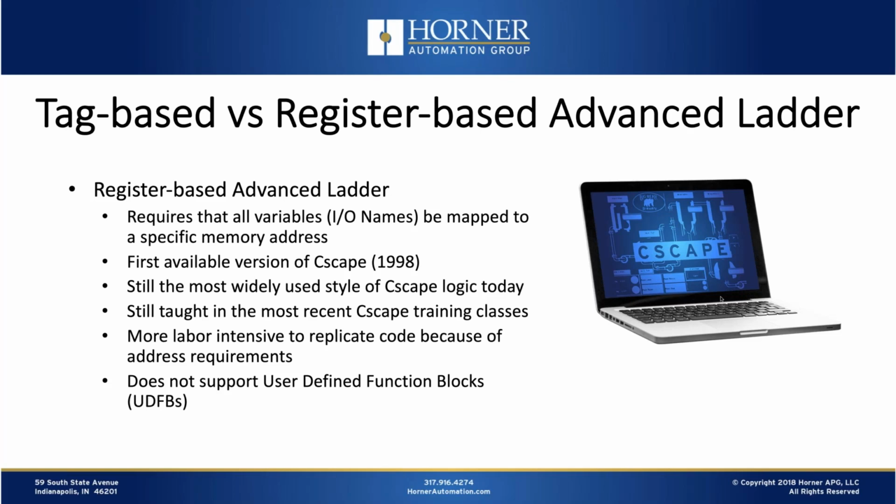Also, the register-based advanced ladder, for similar reasons of addressing, does not support user-defined function blocks. And those are very powerful tools that allow you to replicate your logic or portions of your logic and reuse it in multiple sections of your code.